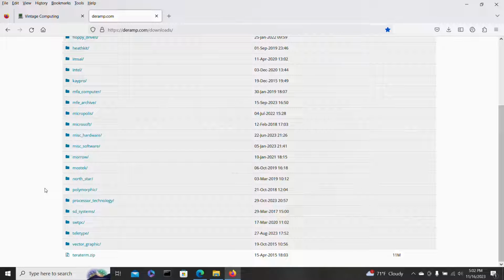And that's where we need to have the similarity, is in the serial interface, because we need to get the data in and out of the Micro Decision via the serial ports. So if we can find software for doing that, that uses the same sort of UART chips as in the Micro Decision, hey, we're 99% of the way to having what we need.